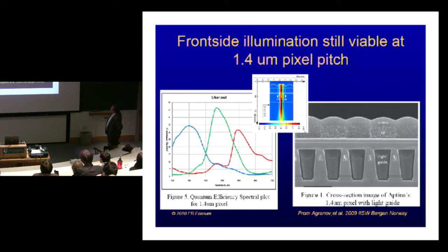And actually, to make these microlenses, sometimes all they do is they just put on a polymer material, cut it into little squares, and then heat it up in the oven so it rounds out. You just got to make the initial dimension and the recipe exactly right so that your cookies come out exactly the right shape.